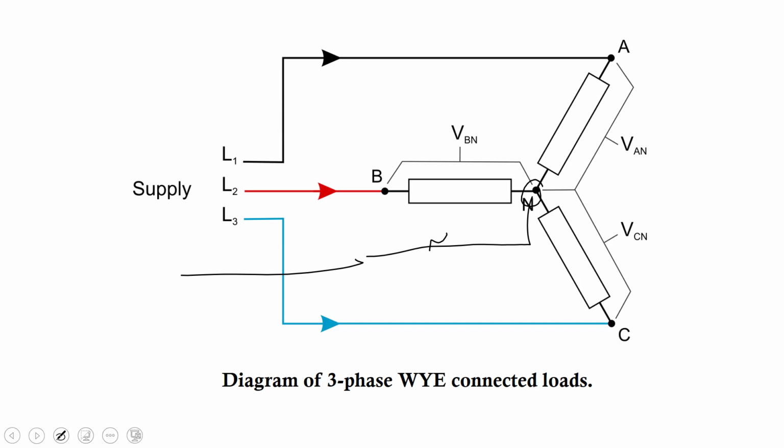So in this diagram itself, it's a three-phase Y connected load, a three-wire Y load, and we can have a three-phase four-wire load as well, and that's where we require a neutral. So the only thing I can think of, top of my head, that does not require a neutral would be a motor.